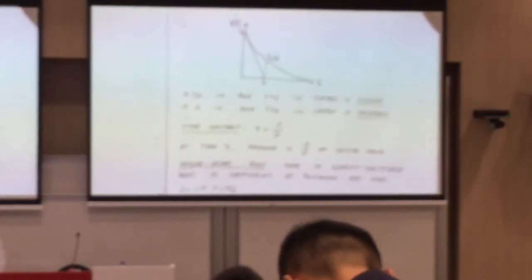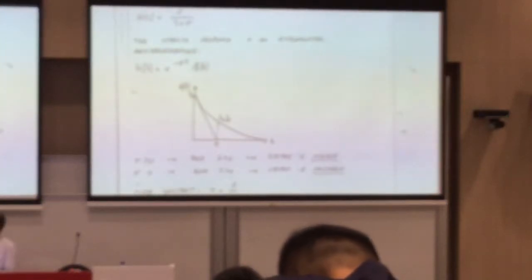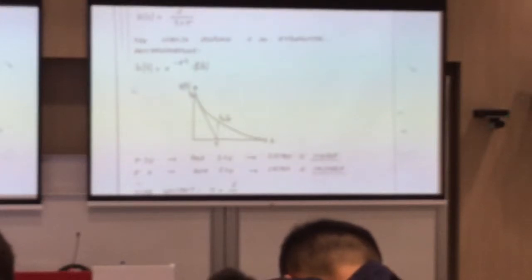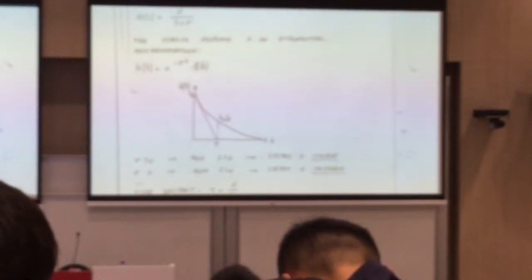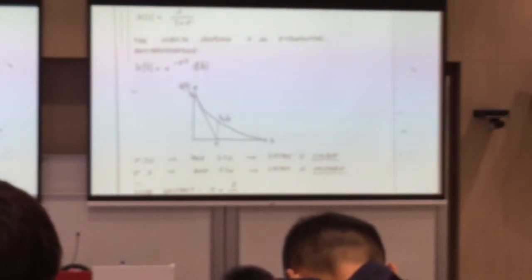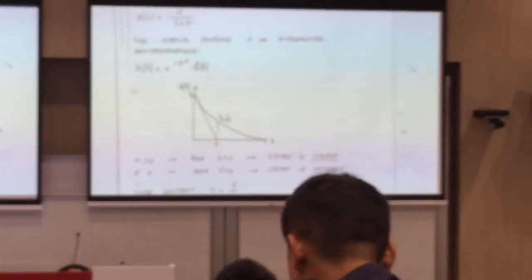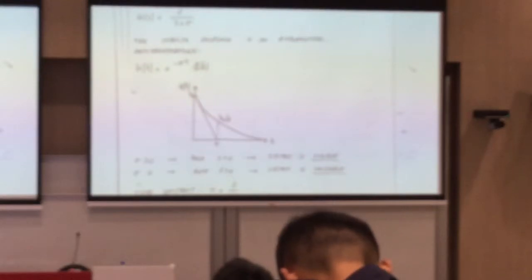And for the analytical part, you also review a typical first order and second order system, right? Because I believe in your dynamics course, you need to cover first order, right? And how to handle higher order? Most likely you are going to use factorization, right? Basically, the tricky part for the math is as long as you know how to solve first and second order. If you got third order, how do you do? Most likely you can do certain factorizations, right? Then your third order becomes a combination of your first and second order. So you can bring that back most of the time.